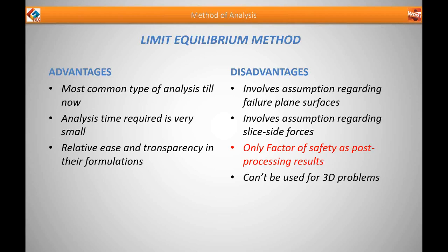The disadvantage of this method is that it involves a lot of assumptions regarding the failure plane surfaces and the slice side forces, and also in the post-processing results the only thing you obtain is the factor of safety, and it can't be used for 3D problems.